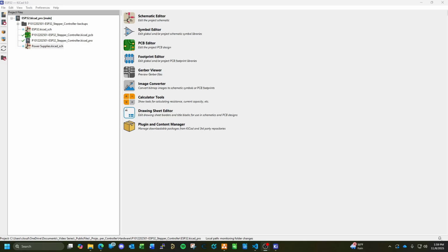All right, well, we might as well begin. So what I'm going to do today is fix just the project and file structure in KiCad, the hierarchy, just to make it flow properly. It's very similar to the hierarchy structure you can create in Altium. So we're just going to go ahead and use it. Well, I prefer to use just a flat hierarchy without creating interdependencies. We might as well go and set up the KiCad project properly.